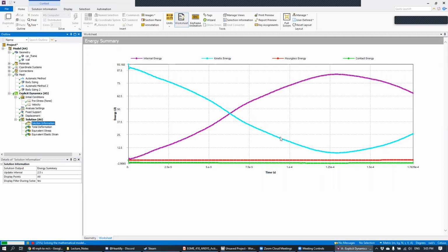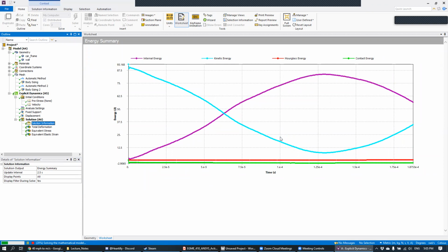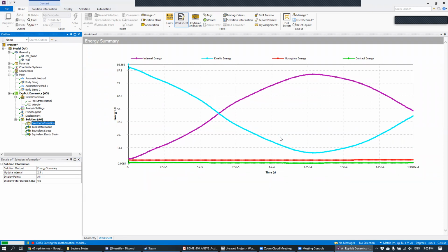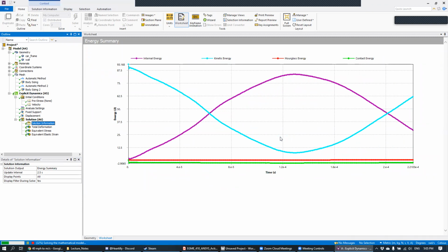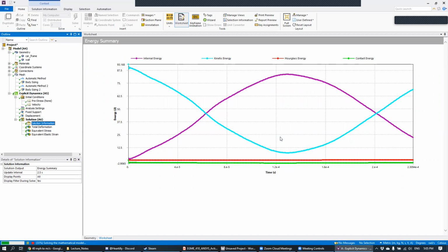Well, even if it's an assembly, not just if it's a single part, just cut it in half, even if it cuts a part in half. Yep, that's totally fine, because if it cuts the part in half, what you can do in Ansys is apply a symmetry boundary condition there. Oh. Yeah. Okay.